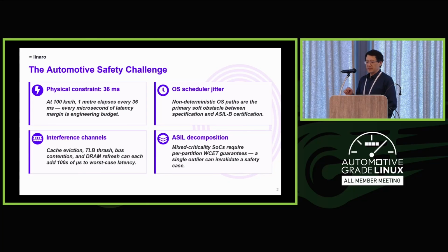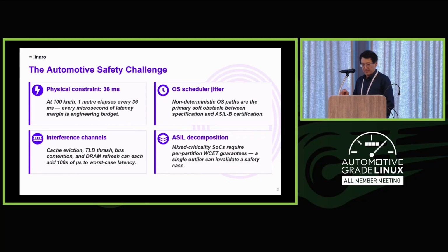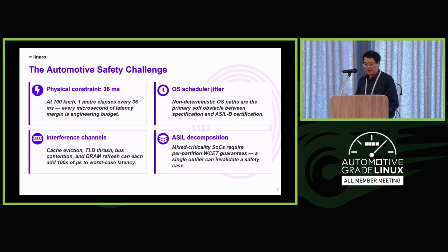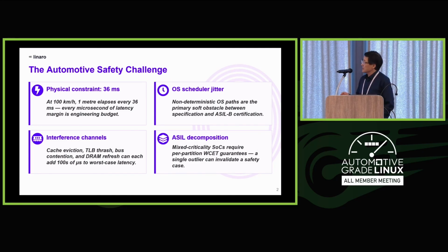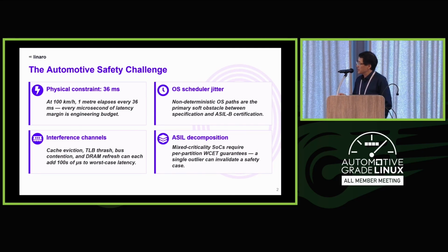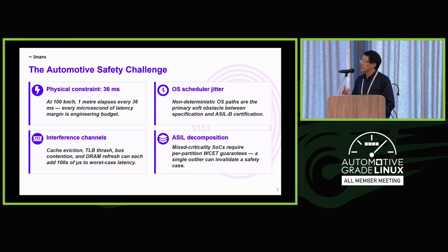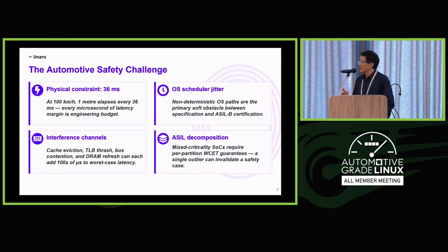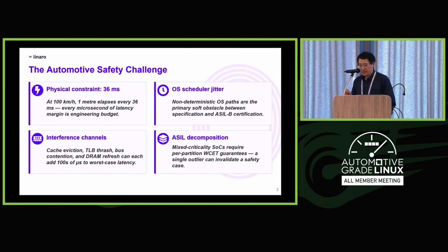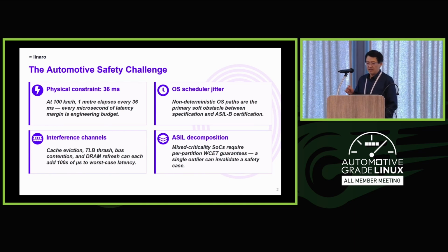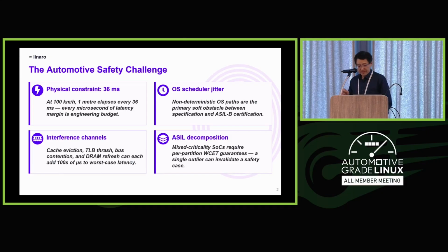The second source of interference comes from your OS, such as Linux RT. Even though the Linux RT patches try their best to make it deterministic, there are still certain non-preemptible paths, where essentially you cannot preempt.